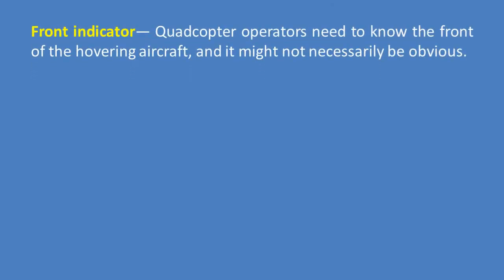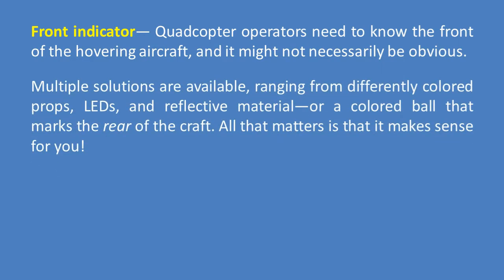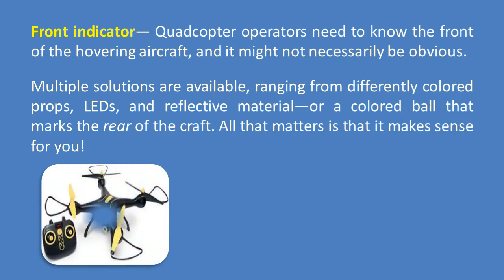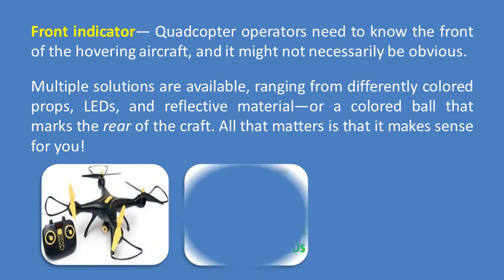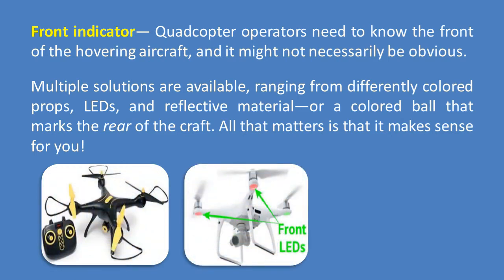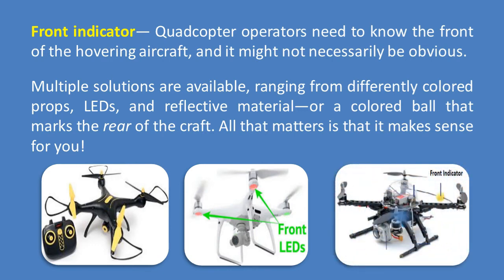Front indicator. Quadcopter operators need to know the front of the hovering aircraft, and it might not necessarily be obvious. Multiple solutions are available, ranging from differently colored props, LEDs and reflective materials, or a colored ball that marks the rear of the craft. All that matters is that it makes sense for you.